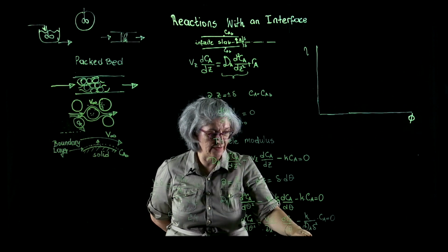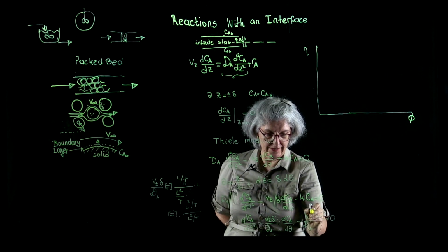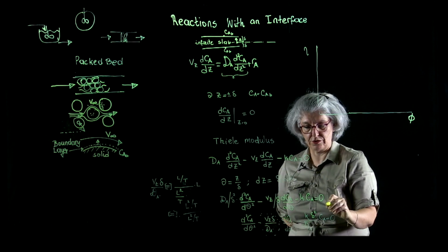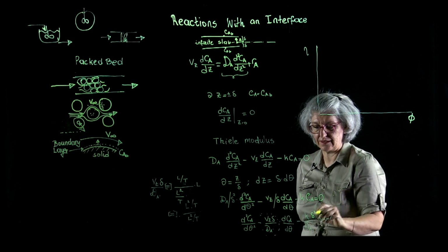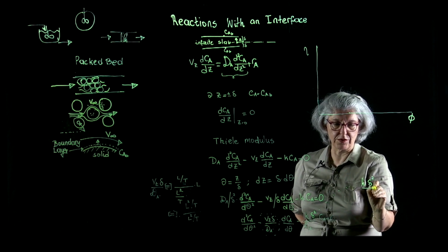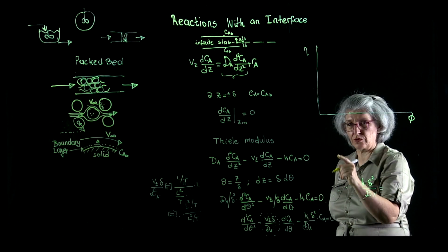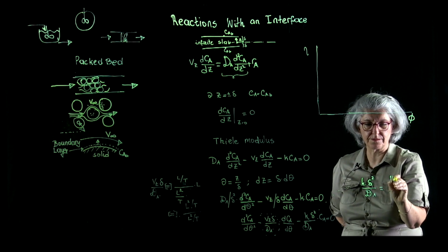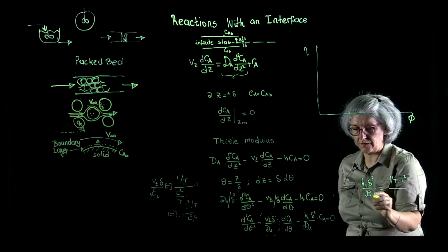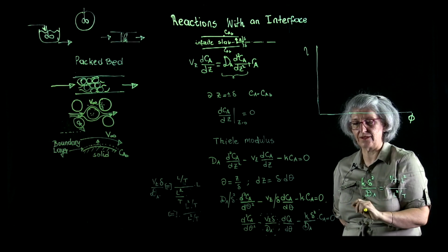Now let us examine this term. Of course, we have to clean that up and make it accurate. So we're going to do the dimensional analysis here. We're going to have k times delta square over D_A. This is rate constant, first order rate constant. It is 1 over time. Delta square is length square. Diffusivity, length square per time. And they canceled one another.